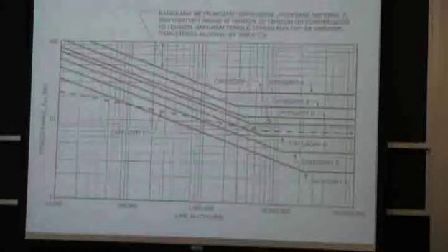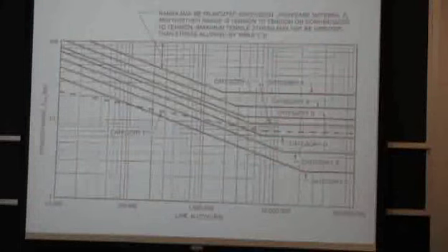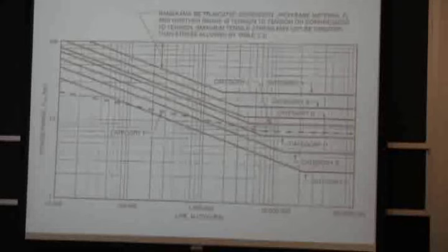It tells you exactly what to do, but it's super conservative. So it tells you if you're using a plain piece of steel, you have an allowable of about 20, say 22 to 25 for the stress range. That's category A here.